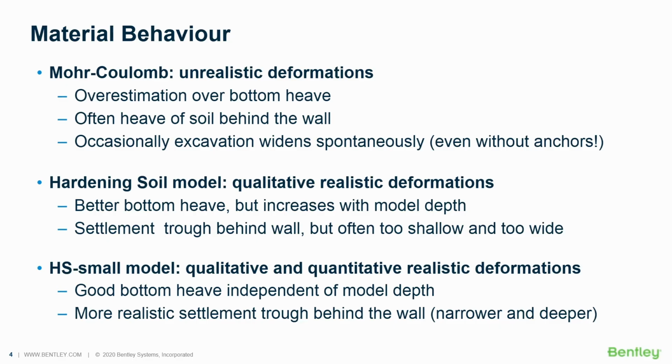Usually from a purely qualitative point of view, the hardening soil model provides a much better displacement and deformation prediction, with a better bottom heave, which would though increase with model depth, and a settlement trough behind the wall which would be much more accurate.